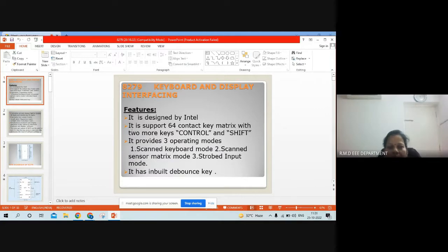to a processor, then during that time the processor needs to check the status of the keyboard, and also it has to refresh the display after each and every operation. While doing so, it will be wasting most of its time in refreshing the display and checking the status of the keyboard. So in order to overcome this, we are going for this IC 8279, with which we can perform simultaneous operation of keyboard and display interface. For that purpose mainly this 8279 is meant, by means of which we can improve the operating speed of a processor, whether it may be an 8085 or 8086 processor.